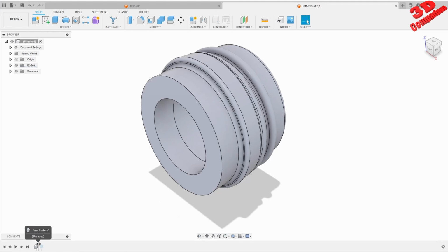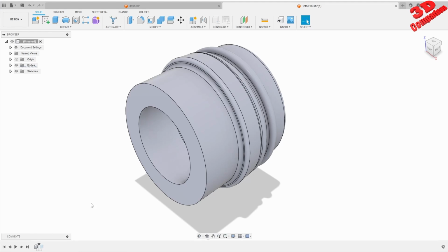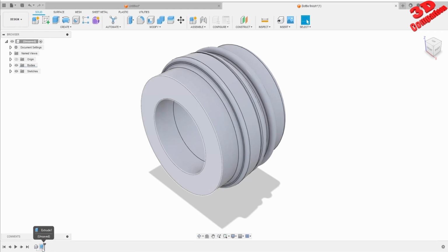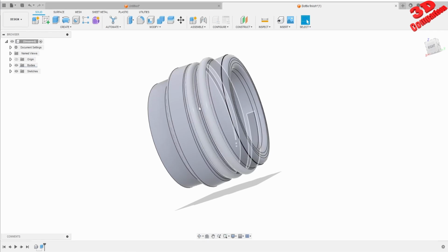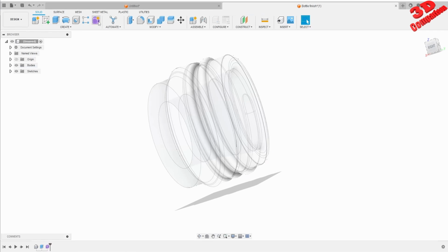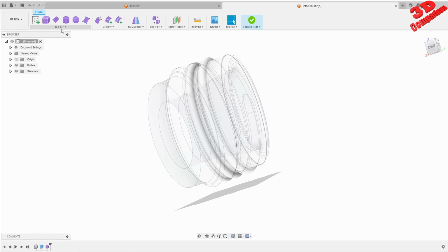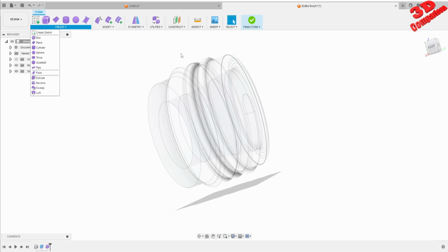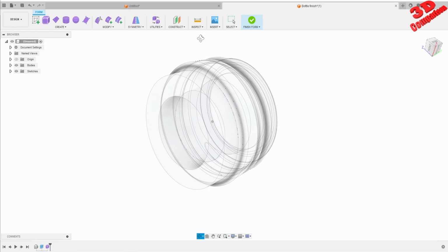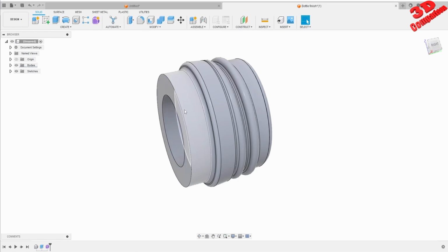So we're going to see this will be the original design, but only after I did that extrusion. Then we're going to have the secondary cut over here. And if you want, for example, to define a bottle, you can start with a form design and you can work with that, for example, for a revolve. And I will do a separate video regarding bottle design within Fusion.